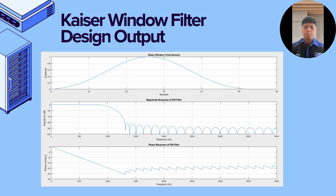Now, for the output of the Kaiser window filter, the first graph shows the Kaiser window in the time domain. You can see it rises smoothly in the middle and tapers at the edge. This tapering is what reduces side lobe leakage in the frequency domain. The second graph shows the magnitude response of the filter.